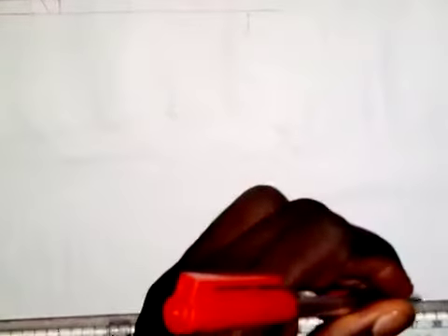So I will draw. Here I'm going to draw a horizontal line at this point. Then with my 30-degree set square, I will draw a line in this direction, and then to turn it to this side, I will also draw a line in this direction.